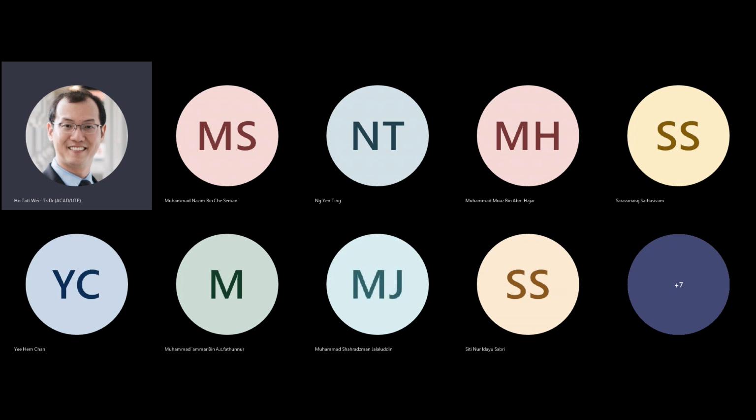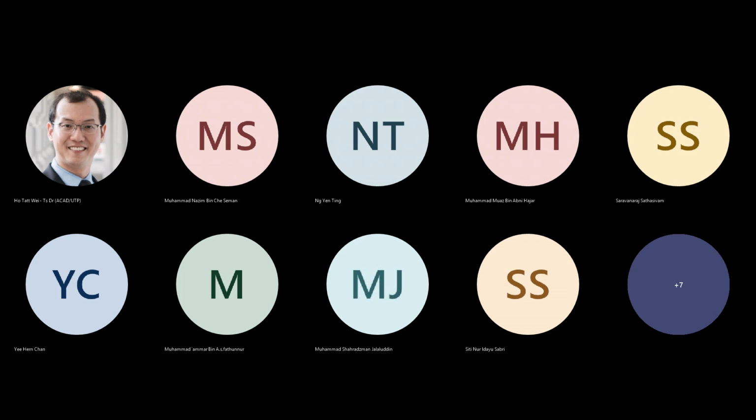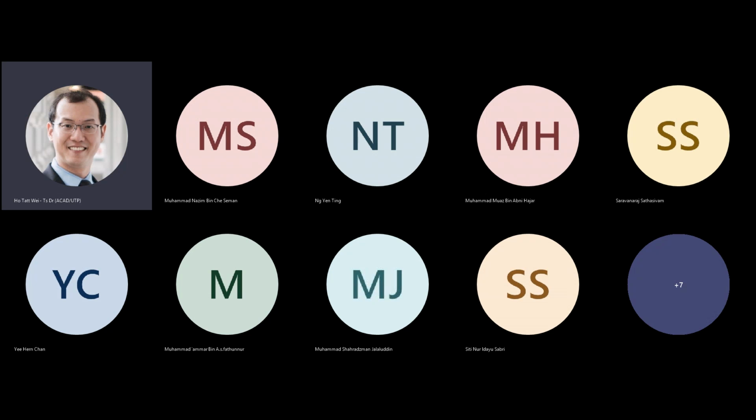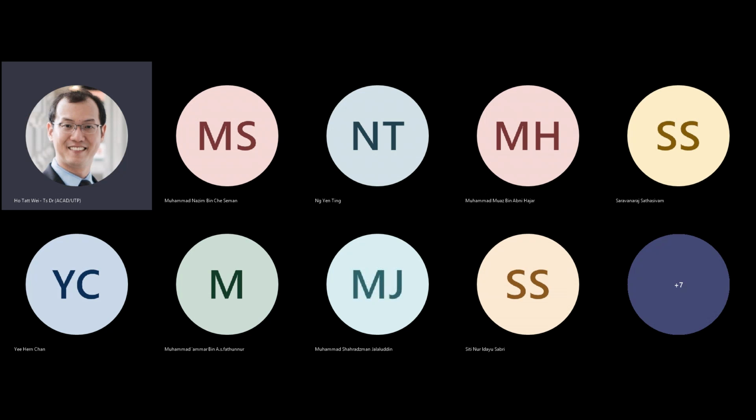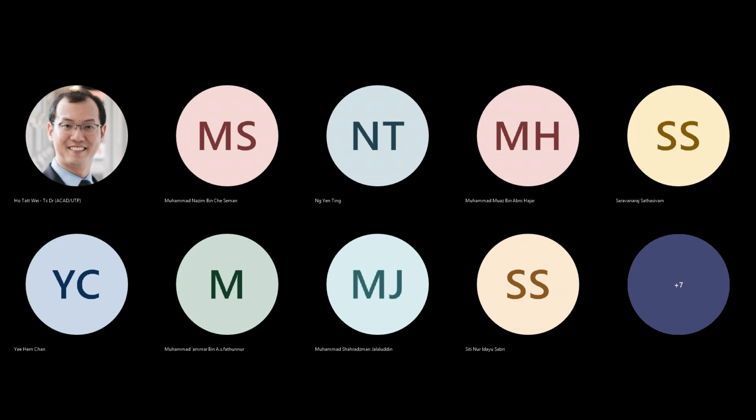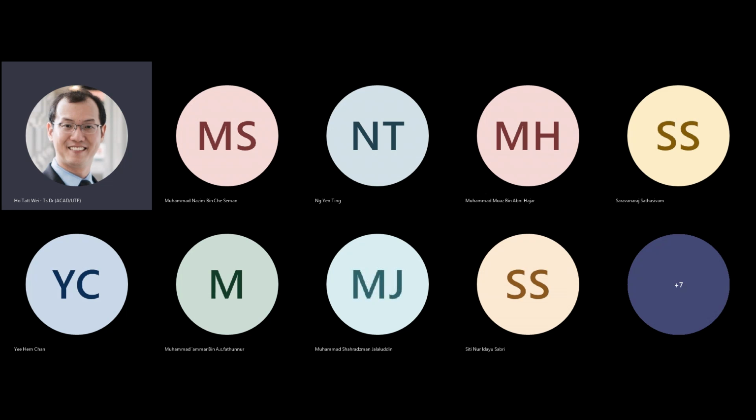So how we draw the switch network, we have two switches here connected to 0. So this is the output here. So two switches in series. And then you have two complementary switches in parallel here. And both these switches are connected to VDD.